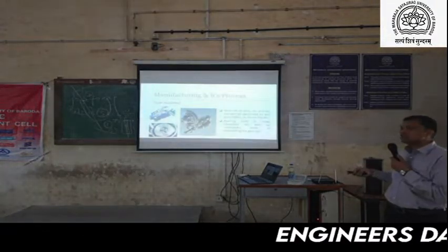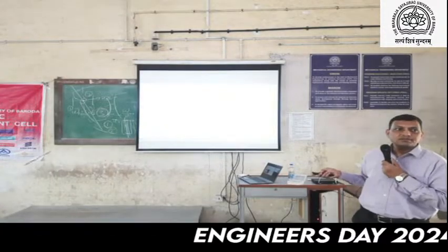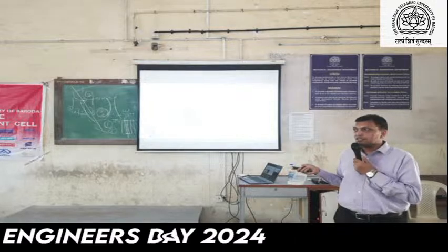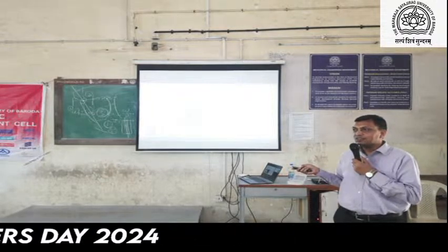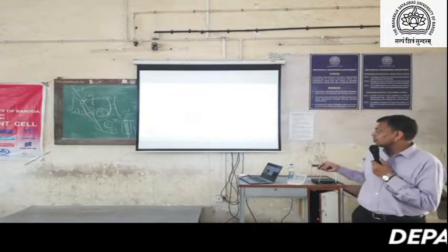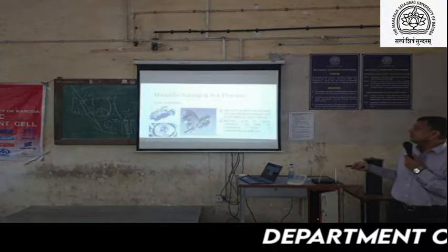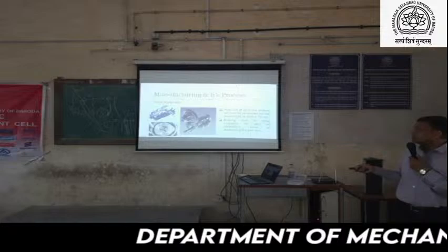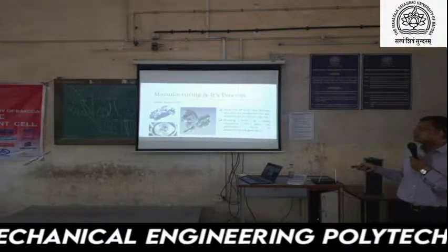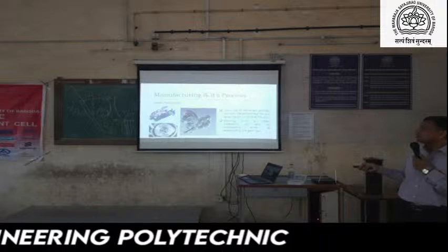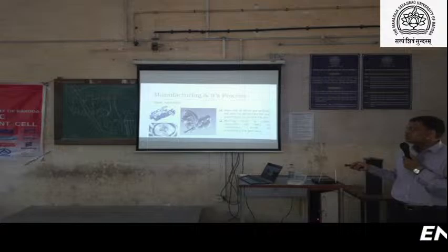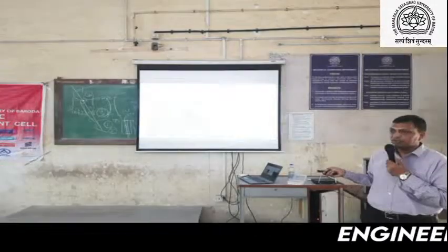How many stage gearbox is this? Anyone? Do you know what the word stage means? A stage means a single path reduction. So here the first is the bevel path reduction, the second is helical, the third is again helical, and the fourth is again helical. So it is a fourth stage gearbox.